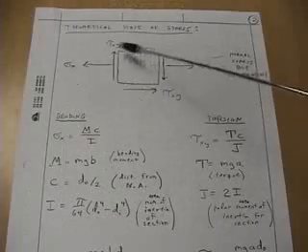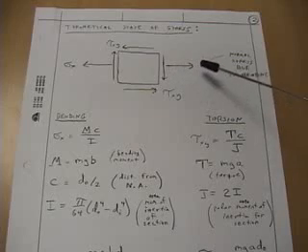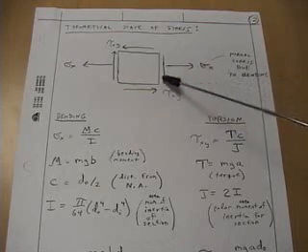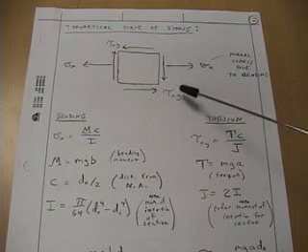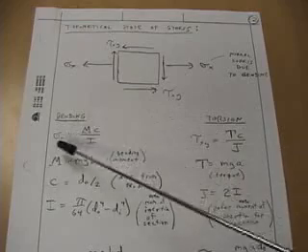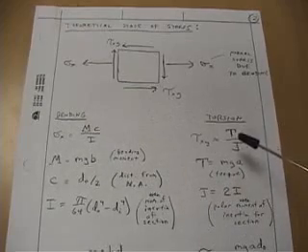This figure illustrates the state of stress on the top of the bar. We have sigma x in the axial direction due to bending of the end load, and we have torsion in this direction due to twisting of the end load. That's tau xy. The bending stress is given by Mc over I, torsion by Tc over J.